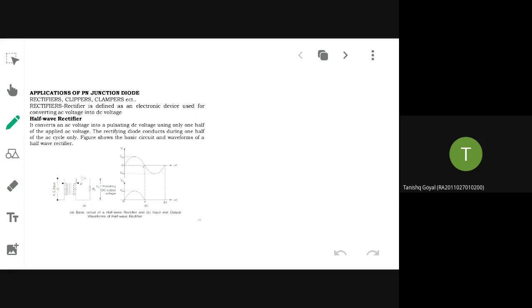So if you want that reverse bias characteristic where the voltage remains constant with respect to the current, then you go for heavy doping of the device, resulting in a special type of diode called the Zener diode. That is why the Zener diode is specifically applicable for one particular application. What is the application for which it is preferably used? Zener diode is used for what application? The voltage remains constant during reverse bias, I told you. So what application?